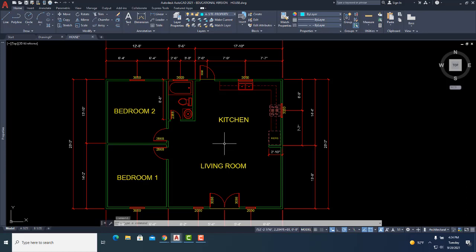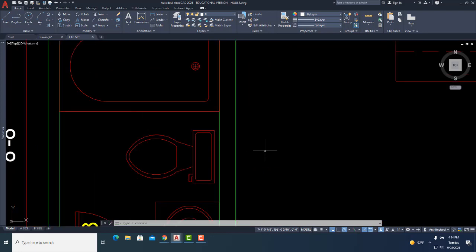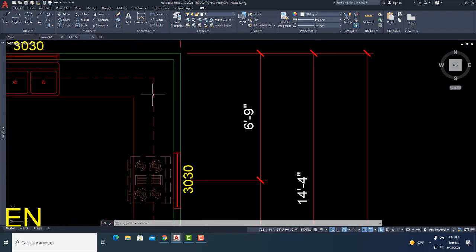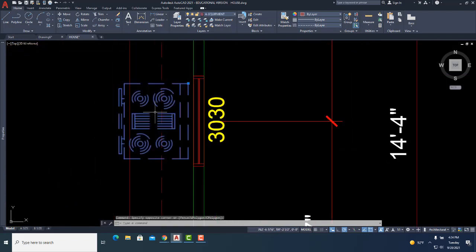Up to now, and when we start doing layers, we're going to create a layer and assign its particular line type to that layer. But a line type, again, there are different line types. The most common one you're going to use is continuous, which is a solid line, just like that, all these. But then you also have some lines that look different, like for example, this one. That's called a hidden line.